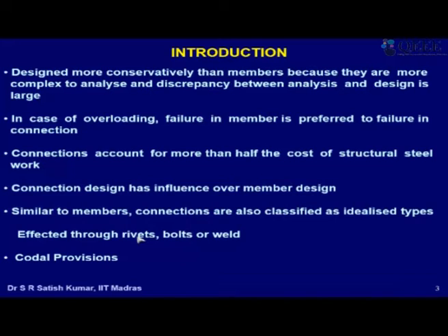That means I need to put a large number of rivets. So you might have seen some old railway bridges, steel bridges or plate girders, where you would see a pattern of rivets. But modern structures don't need so many rivets, and it's easier to put high strength bolts which take larger force, and you need fewer bolts. So your connections become simpler and economical. So rivet design is almost not there. The code doesn't talk much about rivet design anymore, but rivets can be designed if required, following the same equations which are given for bolts.